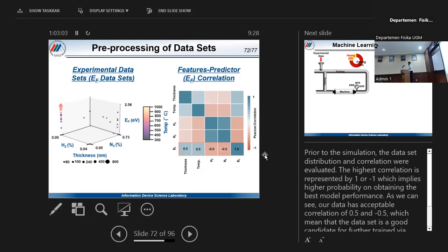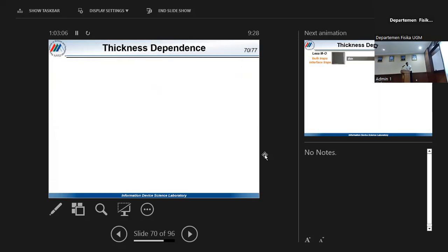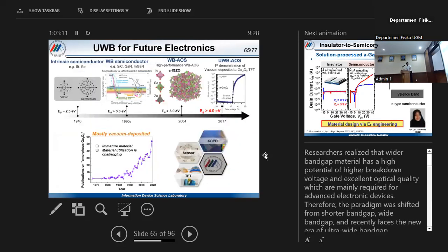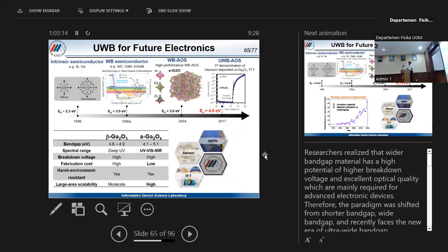Okay, that's a good question. Thank you. I didn't explain it here, but in this plasma, we used an ICP, inductively coupled plasma. It's a special way of generating plasma, and it's very dense over a large area. Usually this ICP plasma is used for etching, so ICP RIE, reactive ion etching. So we use that equipment to generate the plasma.